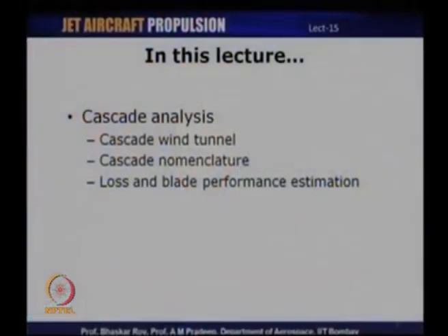Now, in today's lecture, what we are going to discuss is a slightly different topic. Of course, it is still related to the compressors, but it is probably on a simpler level, because what we are going to discuss initially is something to do with a stationary row of blades like a stator. So, in today's lecture, we are going to basically talk about what is meant by cascade. So, we will begin our discussion today on cascade analysis.